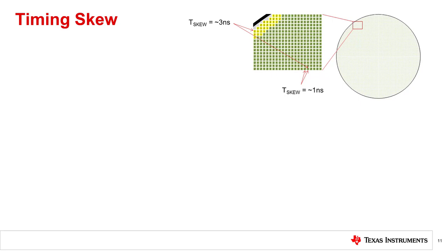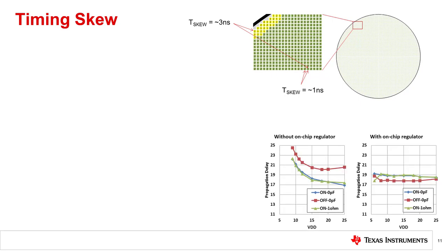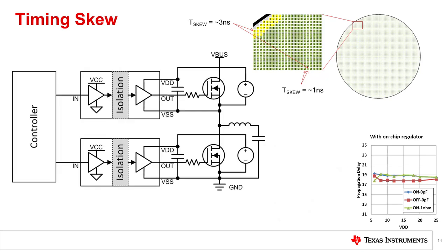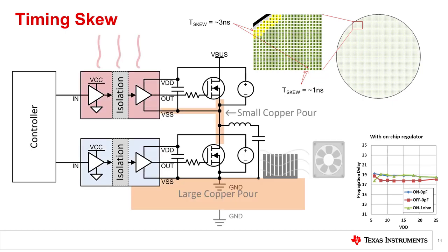Differences in output voltage between the drivers can affect skew through propagation delay changes, though to some extent, on-chip regulators can be used to limit the effect of lower voltage logic elements. But the majority of skew arises from temperature variations between drivers or channels. Even for otherwise identical drivers, power consumption and thermal effects from layout and airflow may be completely different. For applications where timing skew is critical, efforts should be made to match driver temperatures, supply voltages, and lot codes. The test conditions for timing skew can vary considerably from conditions in the application environment.